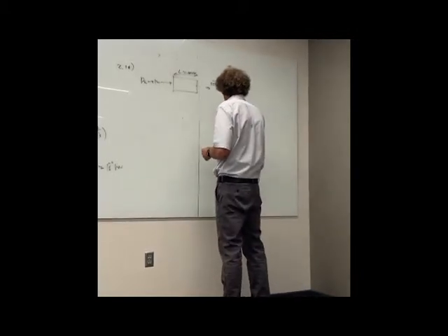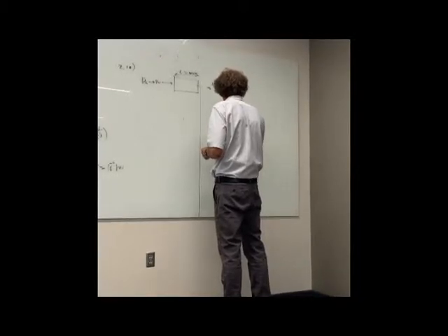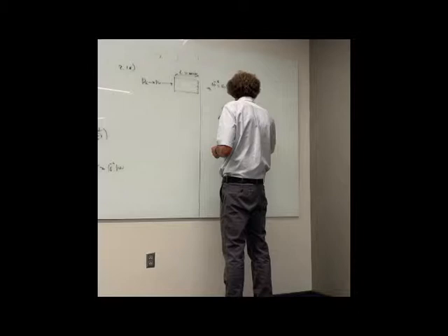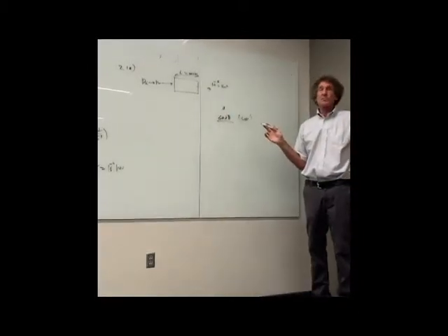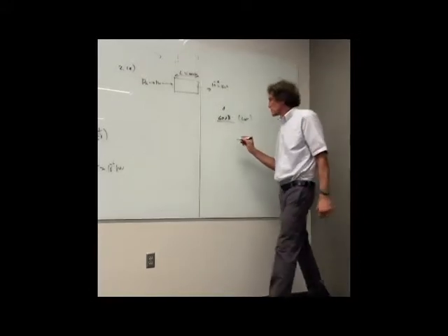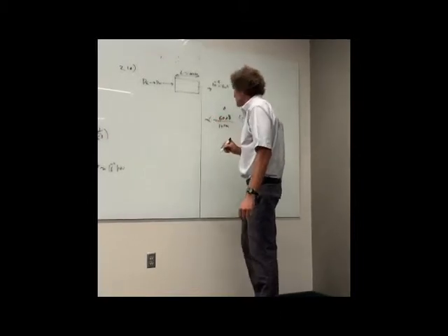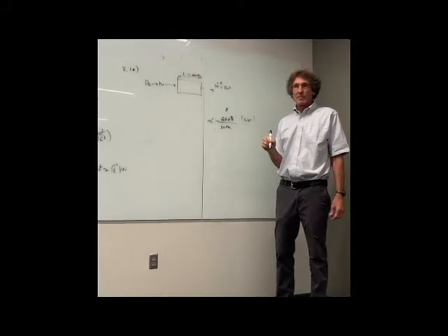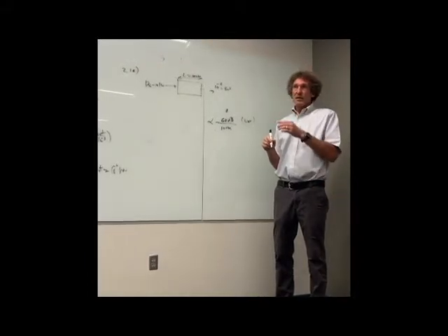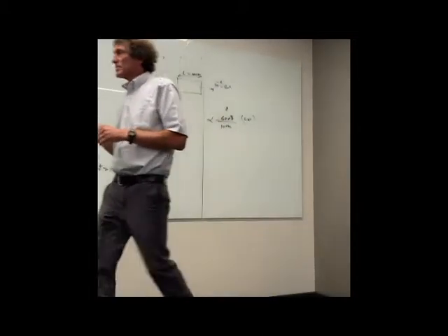So in terms of dB, we have 60 dB of loss, right? And you can put down loss just to make sure. Over what distance? This is how simple this problem is. Over what distance? 100 meters. And that is alpha, or 0.6. That's how easy it is. Are you with me? Did you have a question? What's L equal to? 100 meters, it's the length of the line. Okay. Sorry if it's a little messy.